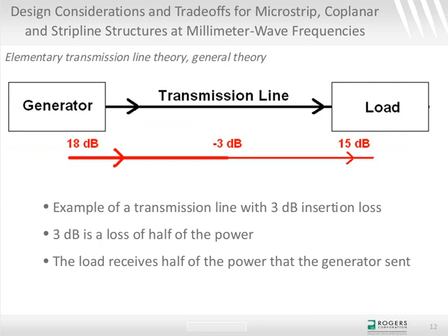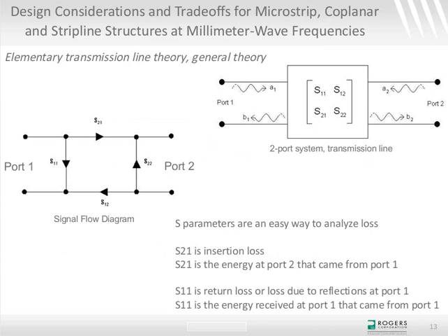And here I've given a very generic, simple example. It's basically saying the transmission line is losing 3 dB of insertion power or loss. But anyway, 3 dB actually turns out to be half the power. So 3 dB may not look like a big number here, but actually it's a big deal. So 3 dB, that number is actually pretty magical to a lot of RF designers because it really is a half power level.